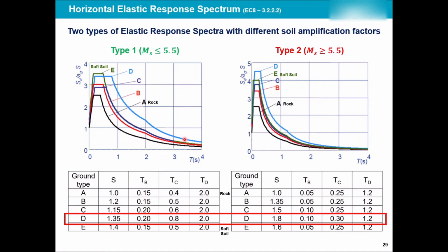The response spectrum which comes out of those formulations is the elastic response spectrum. So we still haven't applied the discount. This is the actual response spectrum of our ground. This comes from the ground according to the period of the structure that we have. Taller buildings, Burj Khalifa; shorter and stiffer buildings, White House. And then this is the spectral acceleration, in this case normalized based on the peak ground acceleration and the soil type.